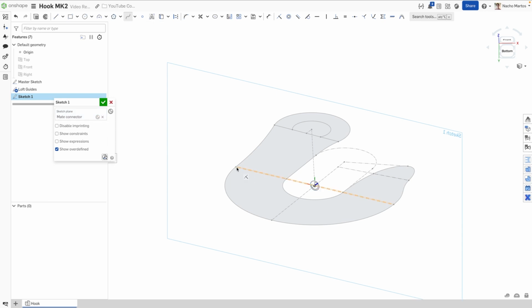We will now use a spline, and the spline is going to go 1, 2, 3 spline points, and we're going to make a second spline, 1, 2, 3 spline points. Now, we can make this go pretty quick once we get our shortcuts down. We're going to select that line and select vertical. We're going to select this spline line, also select vertical.